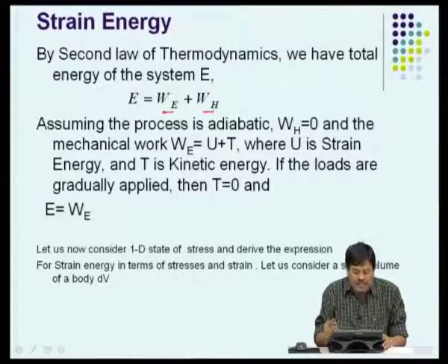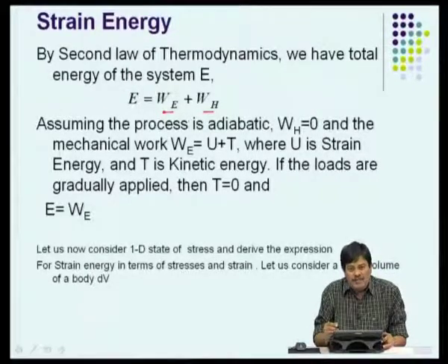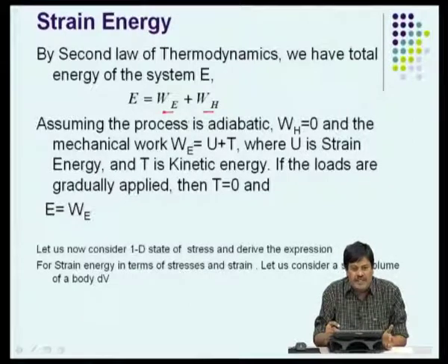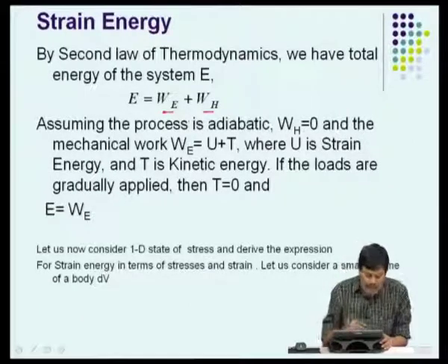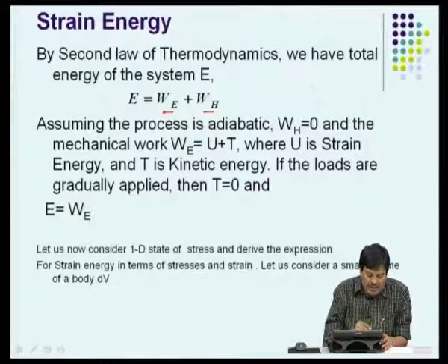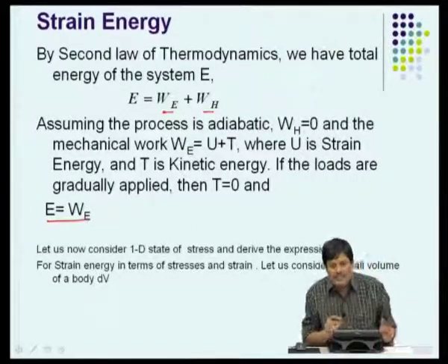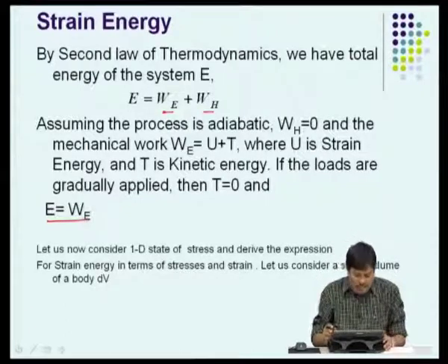That means we assume that WH is 0, and in addition we also assume that the mechanical work is done by forces which are gradually applied, not suddenly applied. So, the forces contributed due to inertia, that is the kinetic energy, is 0. So, the total energy E is equal to the energy done by the mechanical work. We start with this premise and we continue our analysis.